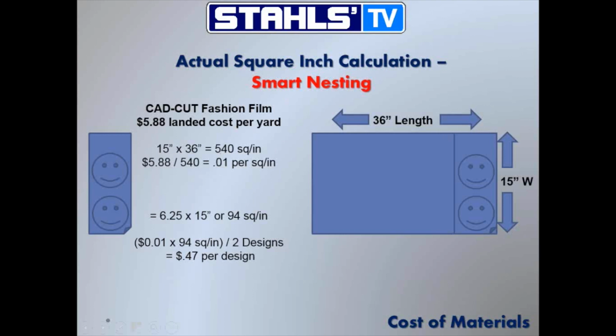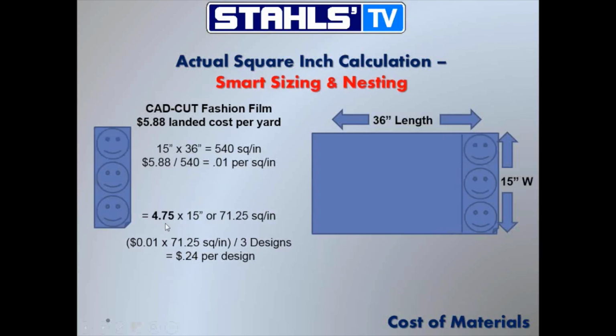The next big thing that I wanted to say is there's also something I like to call smart sizing. So a customer usually doesn't know what size they want their design. So you have a little leeway when you are proposing a design size or sizing for the garment. So it makes perfect sense to make sure you create sizes that can be multiplied to equal your material width to make efficient utilization of your material. So in this sample, what I would do if they came in and wanted a center chest design, instead of proposing a 6 by 6 inch graphic, how about proposing something that's 4 3/4 inches? Odds are they're not going to care if it's a little bit smaller, and that will allow you to nest up a lot more designs.